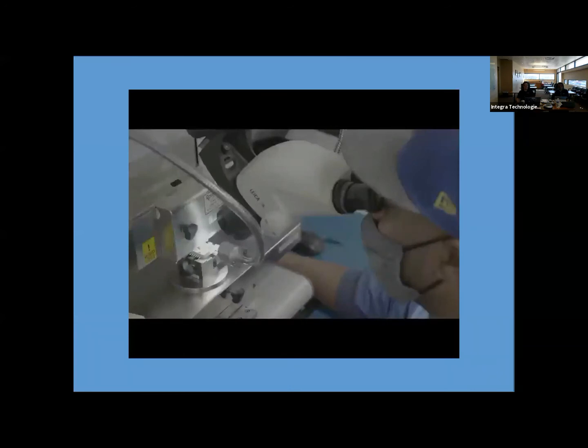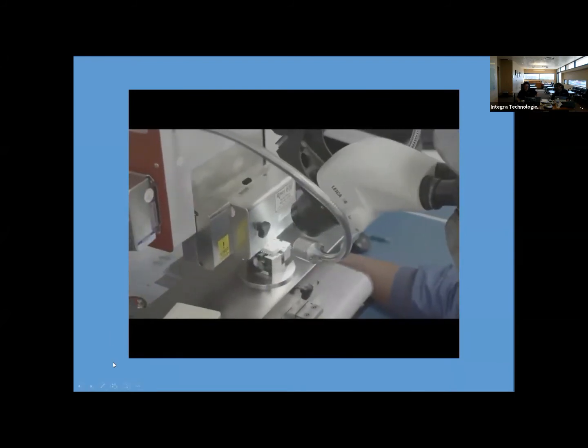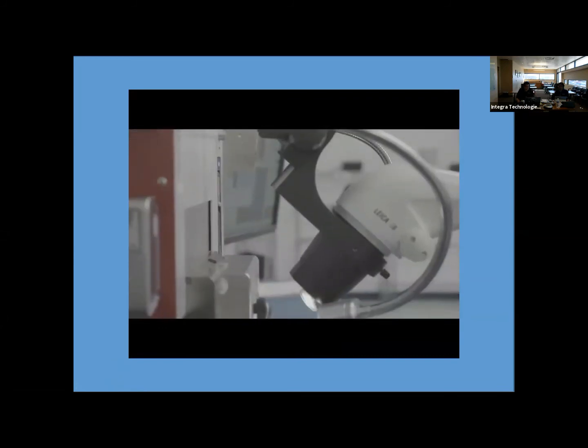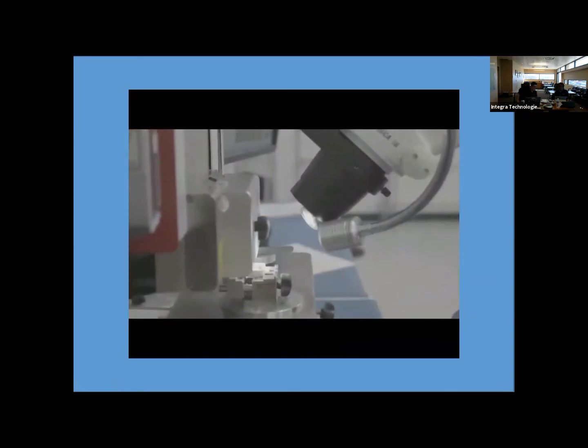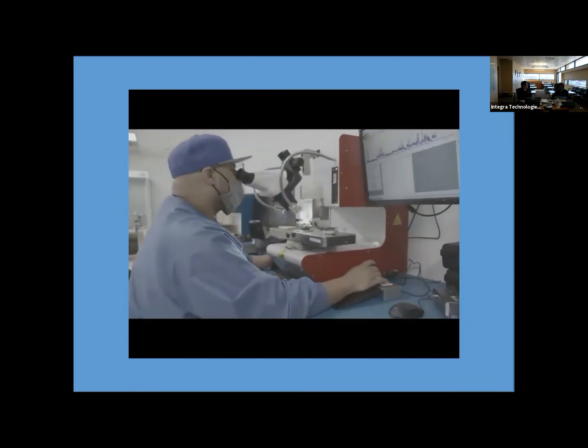This one's pretty good. There's a question. The first question was, do we do destructive bond pull at PEMs? Yes. Well, if you're doing a DPA to MIL standard 1580, it will require you to do the destructive bond pull. And the other question is, is there a minimum limit for the copper bond wire test, or is it in reference to gold wire bond? That's a great question. So copper, now with the 1580 revision C, is to be treated as gold.